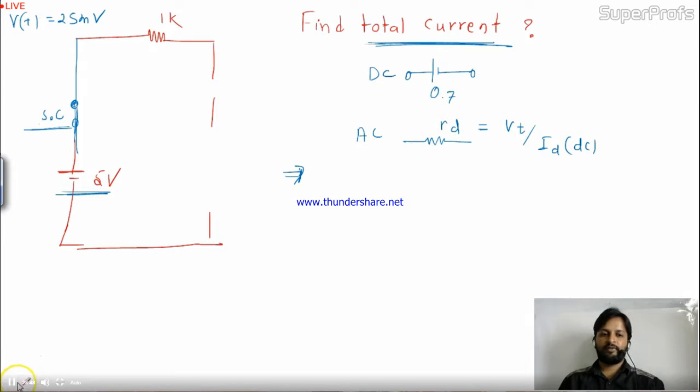When you replace them, your circuit will be, this is 0.7, this is the polarity, because the P portion of the diode is given like this, anode is given like this. So this is 0.7 over here, again 0.7, again 0.7, and 4 times 0.7 actually.